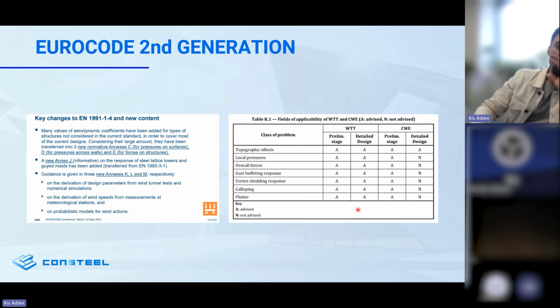And here I would like to emphasize the importance of this use of simulation methods, because this is where we see the value in incorporating this post-processing phase. By using simulation results in a manner similar to the Eurocode, applying more conservative loads to specific zones, and offering the flexibility to override these results within certain limit values for suction, for pressure, and so on, we can achieve a safer design approach.